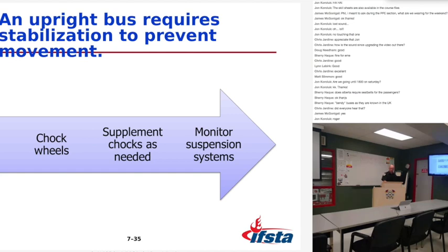Bus stabilization on the wheels: chock the wheels to prevent movement. Use supplemental chocks with a chain, cable, or webbing attached to the bus, and a bomb-proof anchor point if it's on a slope.